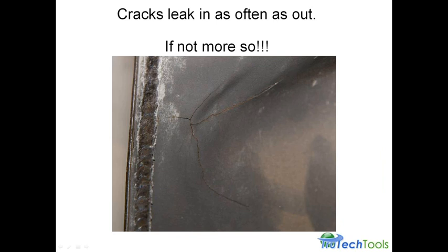If I have a crack in a heat exchanger and I'm pulling in my secondary air through that crack downstream of the point of combustion, I'm not providing that secondary air to the burner. It may be still going through the heat exchanger, but it's not getting supplied to the burner. And all of a sudden I don't have the secondary air that assures complete combustion, and I got a furnace with a crack and it's making CO. So when you get a furnace that's making large amounts of CO and you can't figure out what the heck's causing it, you check the burner, you check the orifices, you check the alignment, start looking for a crack, because you're probably pulling in the secondary air downstream of the point of combustion, and you're starving your flame for the oxygen that it needs to burn completely.